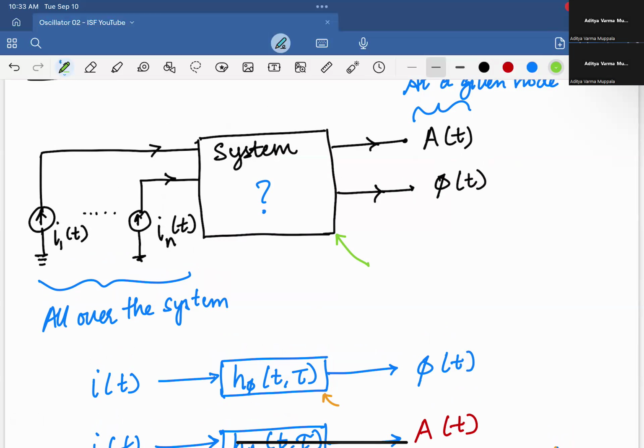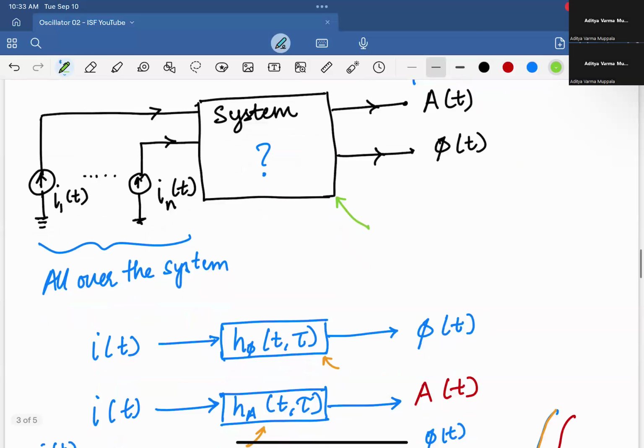So here we're talking about the system that takes a current source input to a phase output. Whereas in the nonlinearity of the oscillator, we're talking about the voltages and currents, what kind of functions those are. Those in fact follow nonlinear dynamics, right? But this system is in fact, for the most part, linear, right? And it's shown empirically. So it's a good assumption.